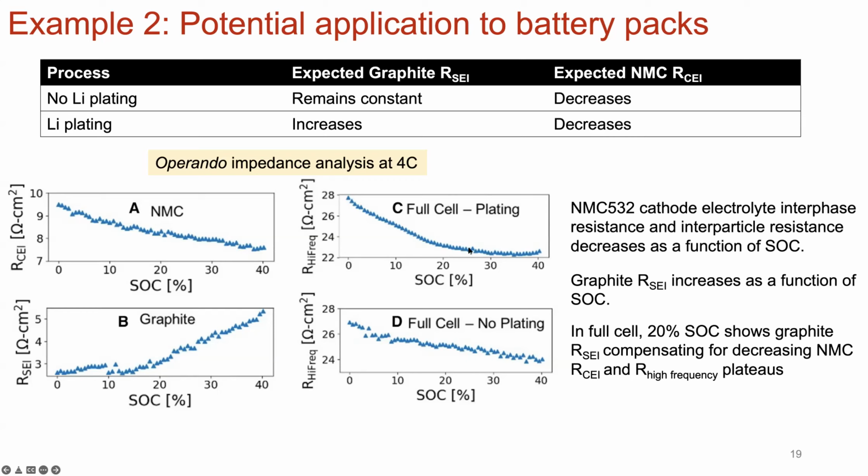And it looks like here you can see the plateau starting at about 25%, somewhere between 20 and 30% state of charge. So that's pretty early. You can tell if there's lithium plating pretty early at 4C. So that's pretty powerful to know of a technique, right?